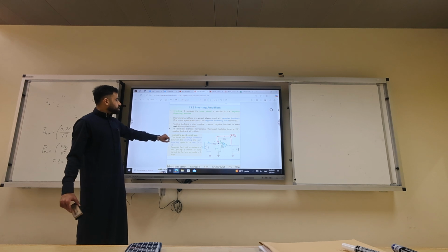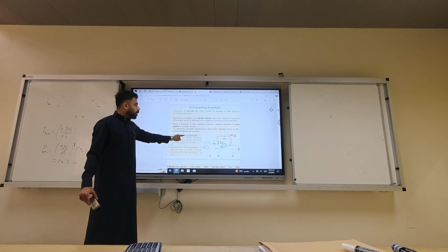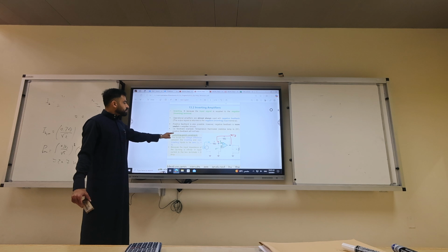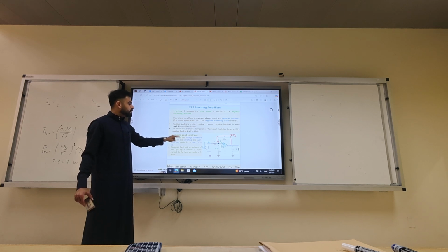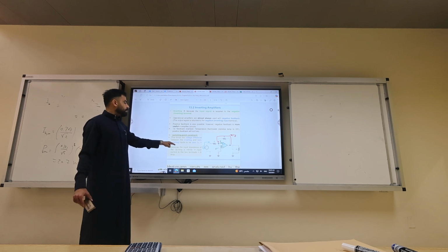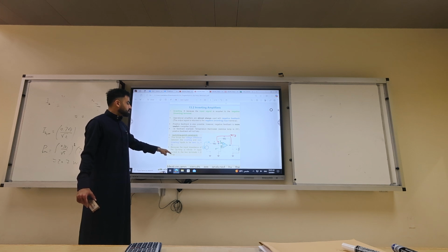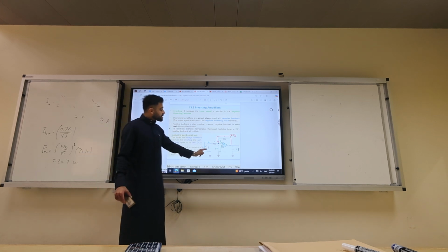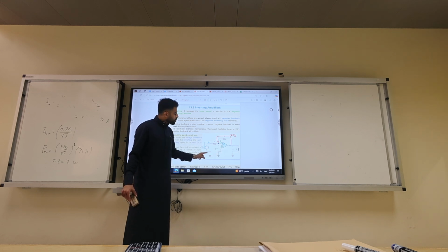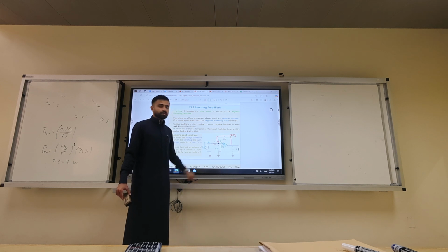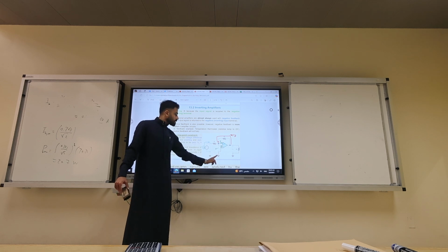There is another important point, what we call the summing point constraints. This forces the voltage difference between the inverting and non-inverting inputs to be zero. Because the input impedance of the op-amp is infinite, input current to the two terminals is 0 amp. What did I tell you? There is no current flowing inside. If there is no current flowing inside, what's the voltage drop here? 0. Because no current. We're connecting a short circuit to the ground.